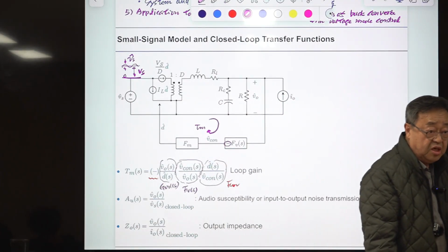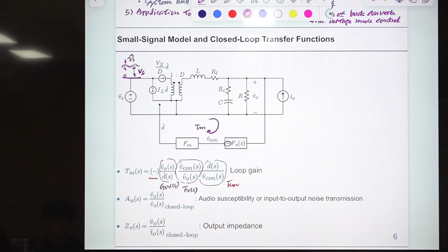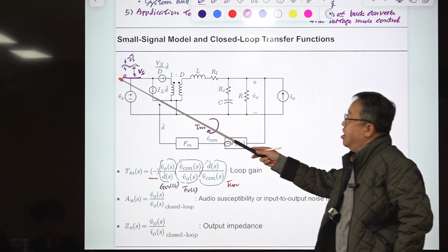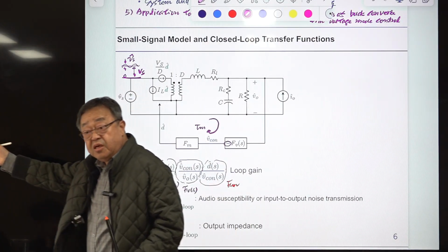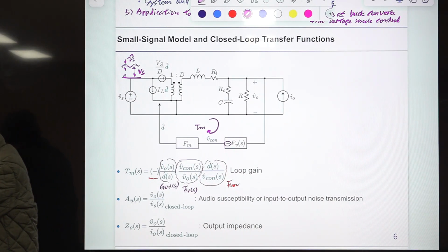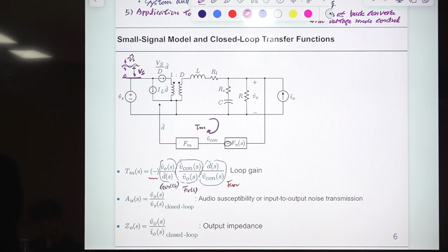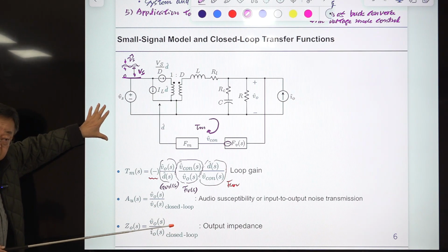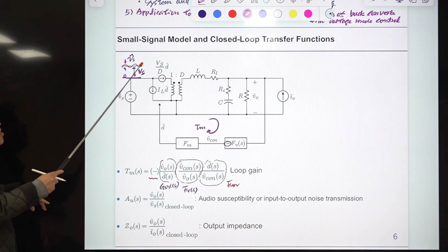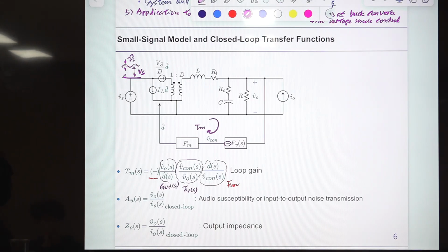Ideally, the input voltage is a constant voltage like a battery, but in practice this voltage is derived from an AC voltage with some rectification circuit. Probably most DC voltage comes from the AC grid with a rectifier in between, and this rectified voltage has some sinusoidal noise component.